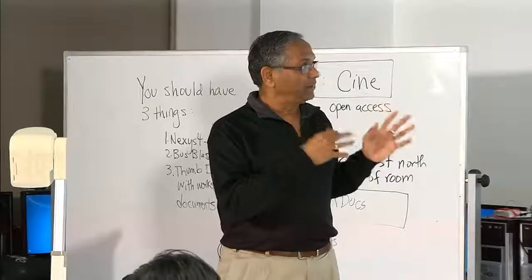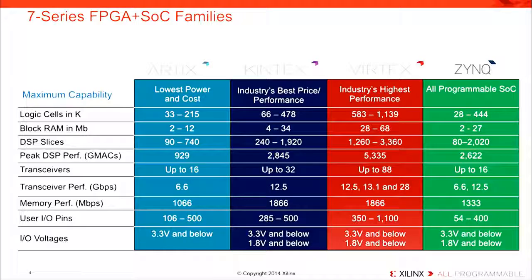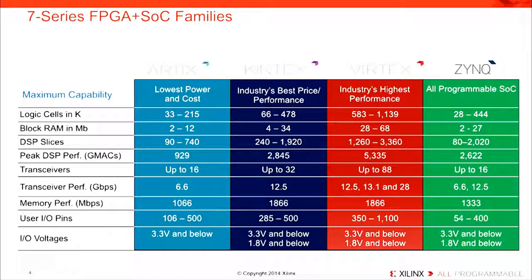And we have 3 FPGA subfamilies, and those are Artix, Kintex and Virtex. Virtex is the highest performance, most expensive family member. Kintex is balanced, and Artix is the low power, less costly chip. If you compare Spartan-3E or even Spartan-6 with Artix, Artix has many more resources. So any design that would fit in Spartan-6 can easily fit in Artix 7.